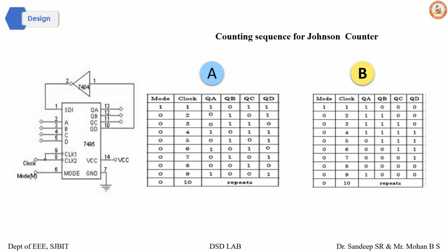So now the desired outputs QA, QB, QC are the outputs. These are the desired outputs, and these desired outputs have to be given as input with respect to port number 2, 3, 4 and 5. So one can observe that A, B, C, D towards the left are the inputs and QA, QB, QC, QD are the outputs. So the first row only should be given as input by making mode high. So set the input, make mode high, and then press the clock pulse. All the data will be transferred parallelly to your output port, that is for QA, QB, QC and QD.